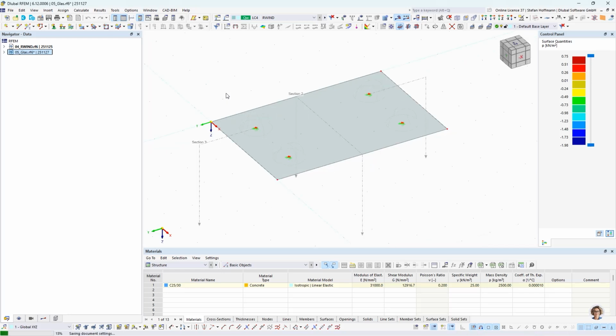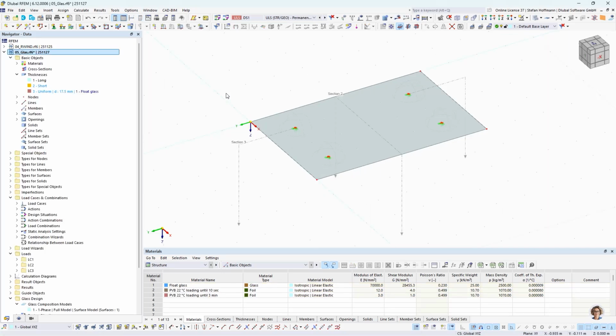The next question is, can I control the shear coupling for laminated glass in RFEM 6? Usually, with laminated glass, the shear coupling is of great interest, because if you have a layered plane where you have two panels of glass and one foil in the middle, one worst case is that you do not take the shear coupling into account, having big deformations and stresses only in the glass planes. That is why we use laminated glass, so that you can take into consideration the shear coupling.